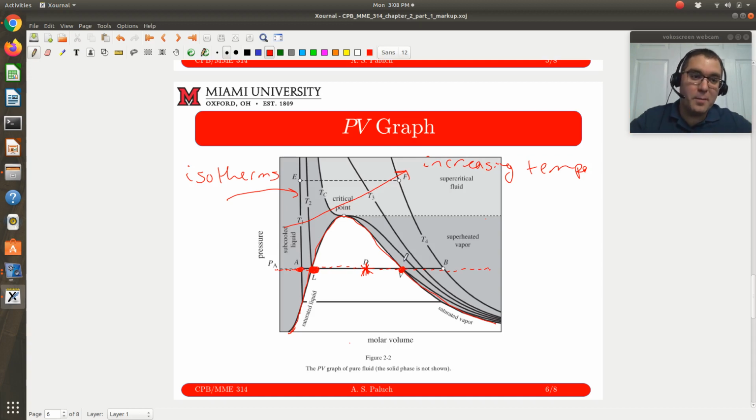I have to heat it up relative to the corresponding value at saturation. So to the right over here, we have what's called a superheated vapor, a single phase vapor region. To the left on this phase diagram, I call this subcooled liquid. It's equivalent to compressed liquid, and we'll get to that name on the next phase diagram. Hopefully that's making sense.